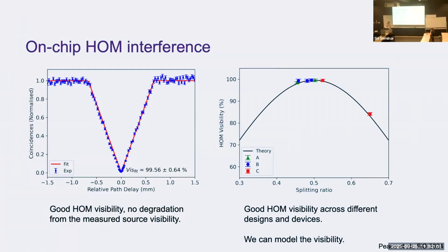Like if you remember the 10 mode device earlier, it will be very sensitive to the exact width of the waveguide, to the exact distance of one waveguide to the next. It's going to be very sensitive to those fabrication errors.